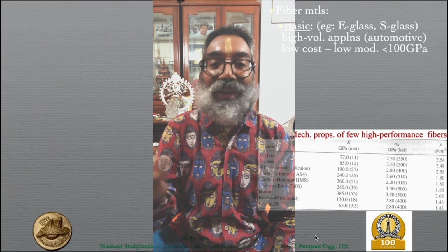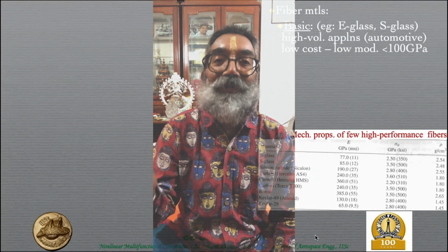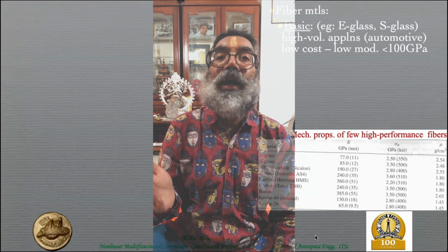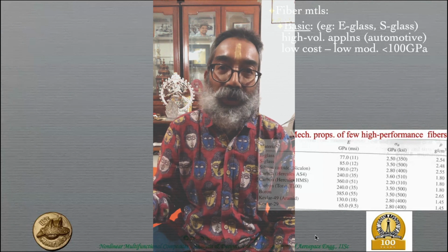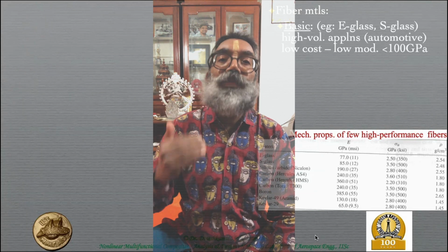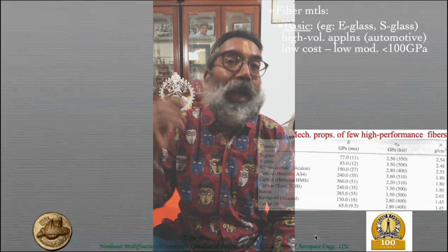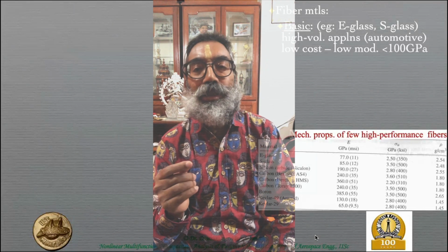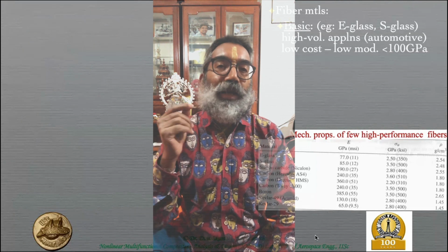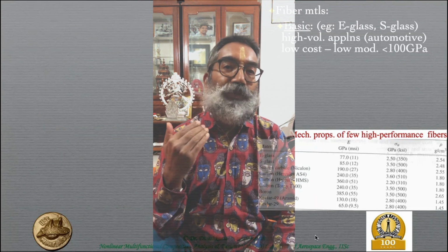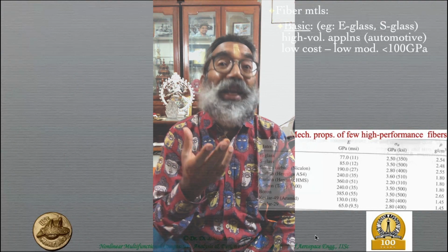See, eventually it becomes like curve fitting. So you're trying to improve it based on the curve fitting, and that is acceptable where you do not have what are called phenomenological models. That is the ultimate, a physics-based model where you understand the physics that is happening at the damage level, because the damage mechanics is highly complicated here. There can be damage either in the fiber or in the matrix or in their interface, what we call as fiber breakage or fiber micro buckling.